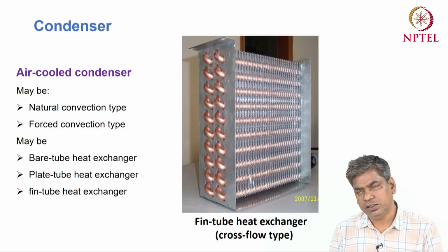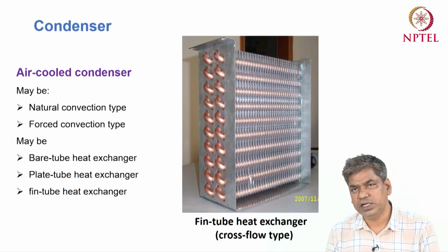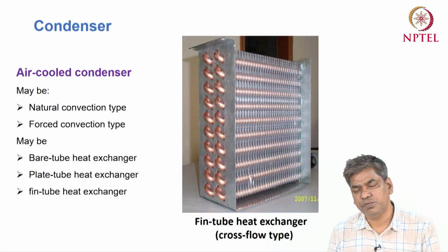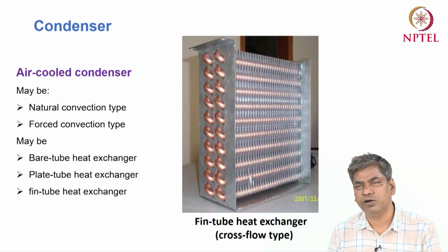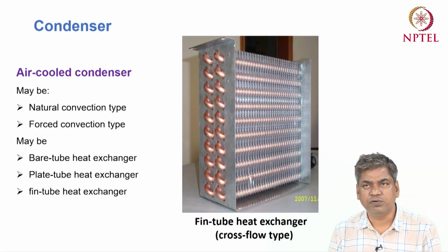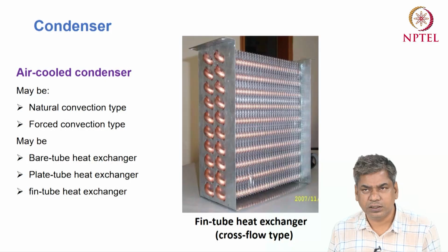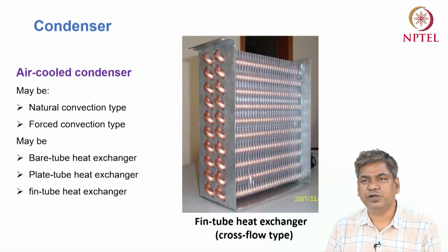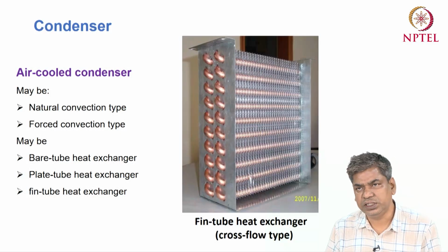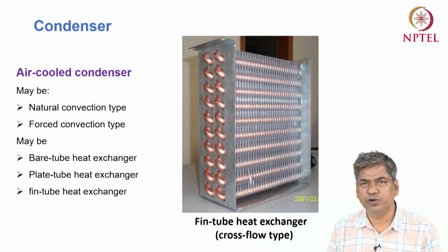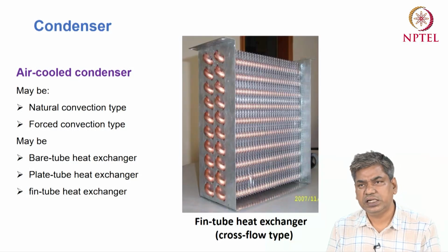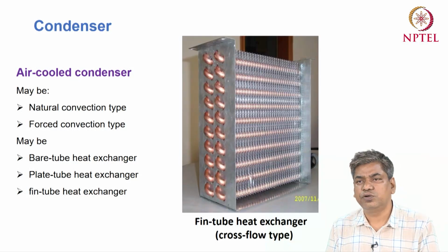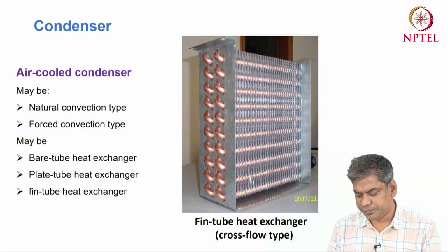Also, depending on the direction of flow of the refrigerant, or the air or the water, whatever coolant we are using, the heat exchanger may be a parallel flow heat exchanger, or a counter flow heat exchanger, or a cross flow heat exchanger. So that air cooled fin tube heat exchanger is basically the cross flow type heat exchanger.